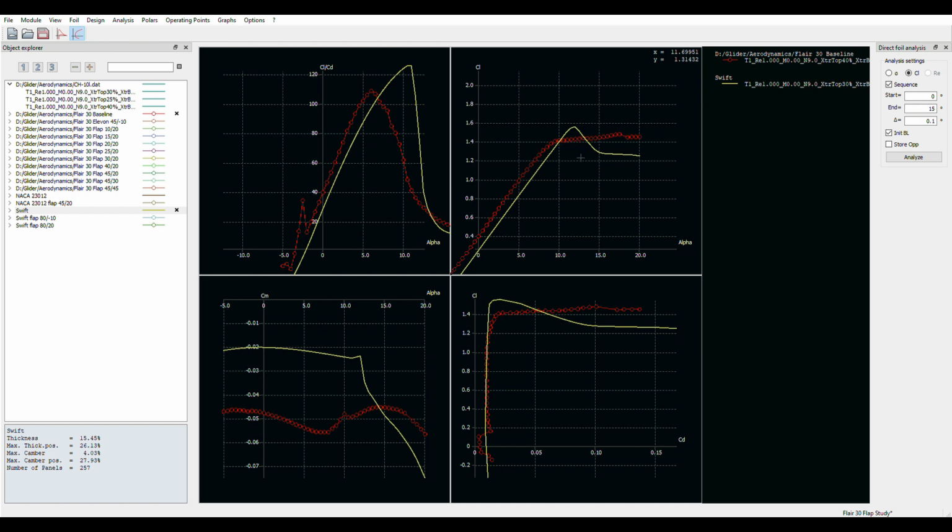And by combination of washout and other factors, you can soften this stall here. And we see it has a fabulous CL over CD. Blows the doors off of the Flair 30, which is over here. They're way up over here. And they can pull that lift to drag ratio at a pretty high angle of attack. Maximum L over D is just before stall.